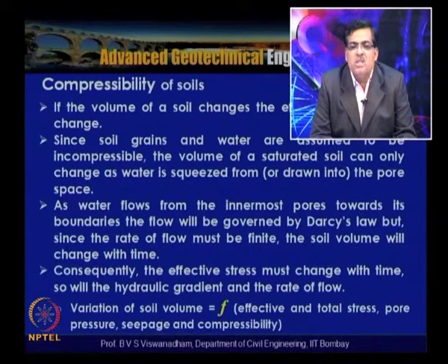Since the soil grains and water are assumed to be incompressible, the volume of a saturated soil can only be changed as the water is squeezed from or drawn into the pore space. As the water flows from the innermost pores towards its boundaries, the flow will be governed by Darcy's law, but since the rate of flow must be finite, the soil volume will change with time.